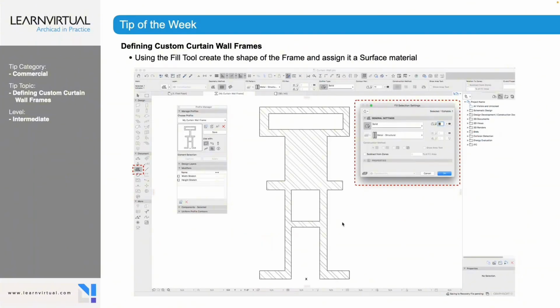So in this case, if we wanted to create a frame, we would simply start to edit and create that frame. Now, the first thing you want to do is to open up your fill settings and make sure it's set to show the type of fill, because in order to create any sort of profile, you need to use a fill. The fill is what Archicad uses as the shape to extrude that shape.